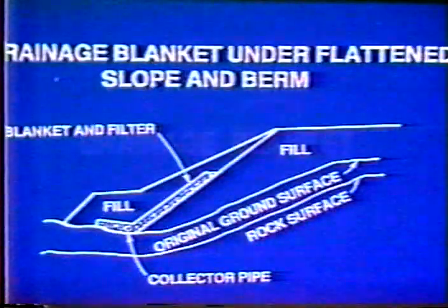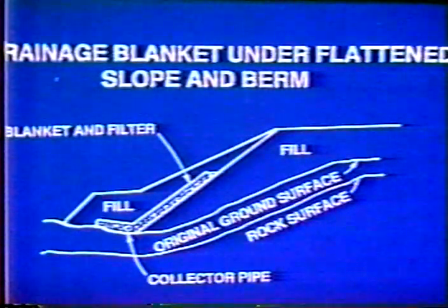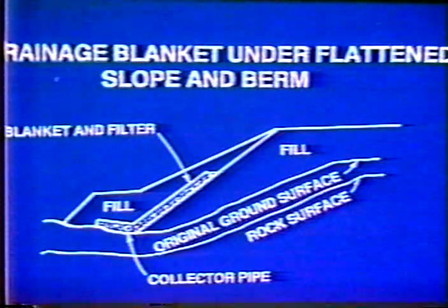Okay, we're talking about subsurface waters and the control of subsurface waters. Another technique, and I'm going to emphasize this in the course, is using drainage blanket. This technique is used with a lot of the other repair methods, or in combination with them, such as slope flattening and berms and so on. Let's take a look at some different situations here. We showed this earlier in the session.